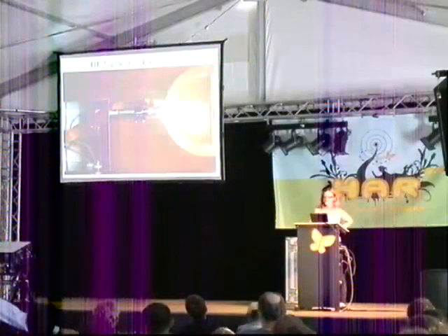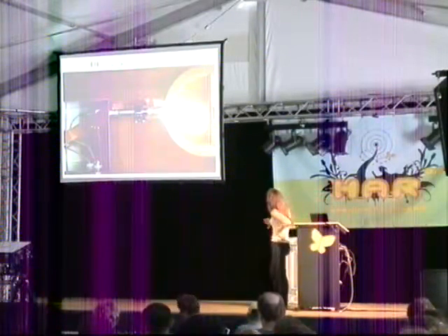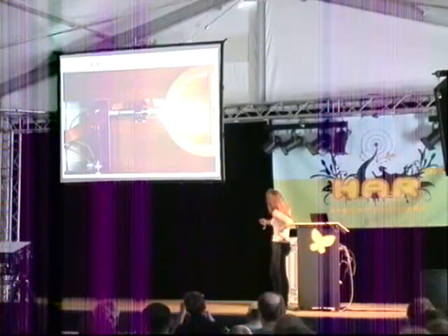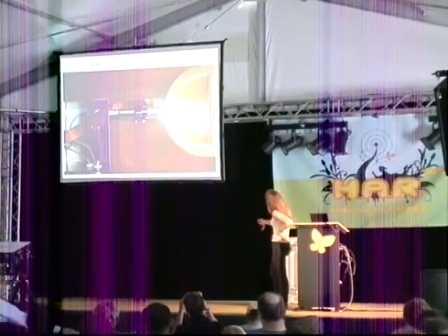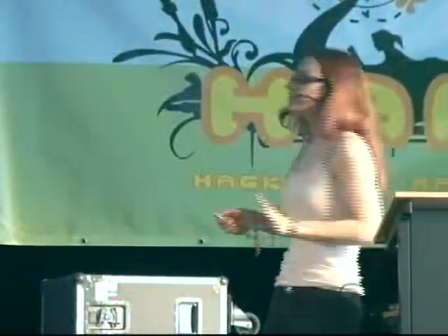Now, going into the RF system, here's just an overview of that. Here, top view of the cyclotron body with one of the electrodes and then feeding into the RF box. There'll be a more detailed picture of that in a few slides. So the way this works, you saw in some of the earlier slides that there were two D-shaped electrodes where one of them would be at a negative voltage while the other would be at a positive voltage, and then they'd flip-flop at the cyclotron frequency.